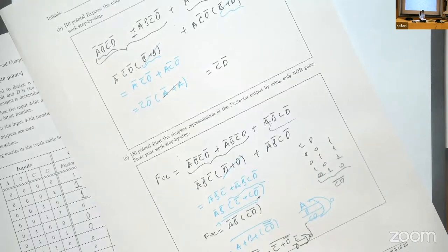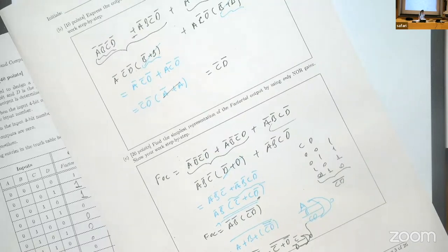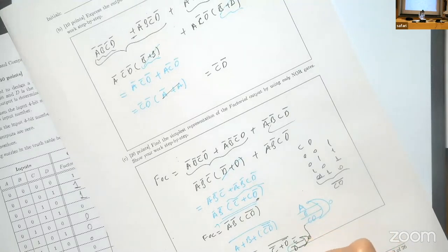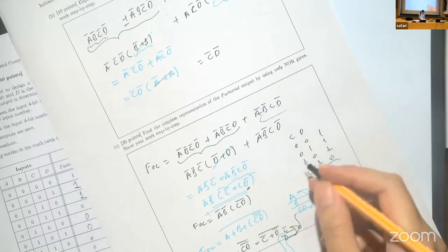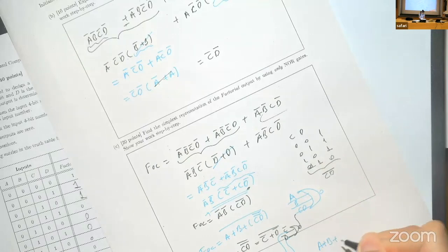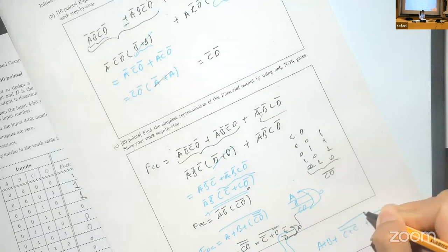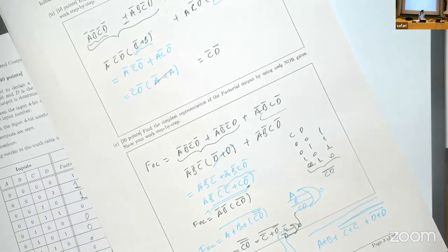And then you will need to do the same thing for D naught. So it's also a NOR of D with itself. Instead of C, you need to have a NOR gate with 2 C's. And instead of D, you need a NOR gate of 2 D's. And if you merge everything, you have A or B or C naught or D naught, actually a NOR of these two things and everything in a NOR way. And this is how you can represent the factorial output using only NOR gates.